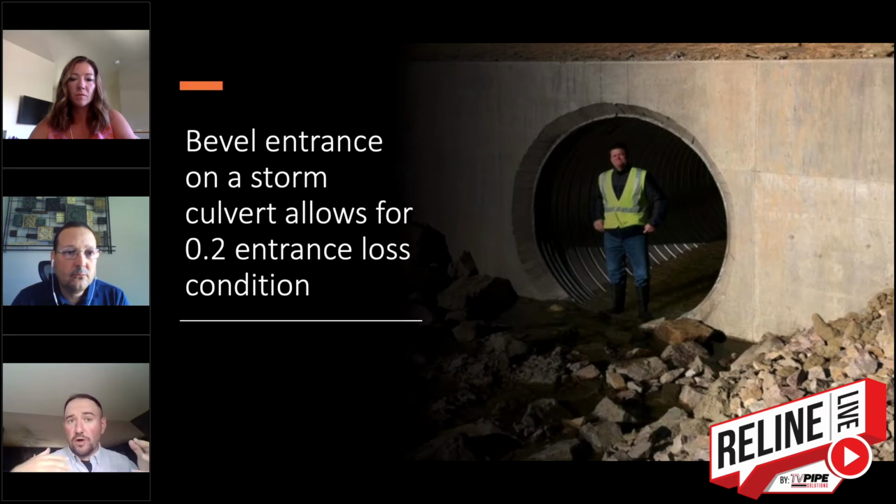So they've already got scour problems there from washout over the years of just a non-protected inlet or invert, excuse me, right? And water moving around those outside edges, what we call piping, right? Water moving outside the pipe. So putting some stone in there, adding some riprap, trying to protect scour from happening in and around not just the pipe, but if there's head walls and wing walls, those can be scoured out too. So you want to protect them.